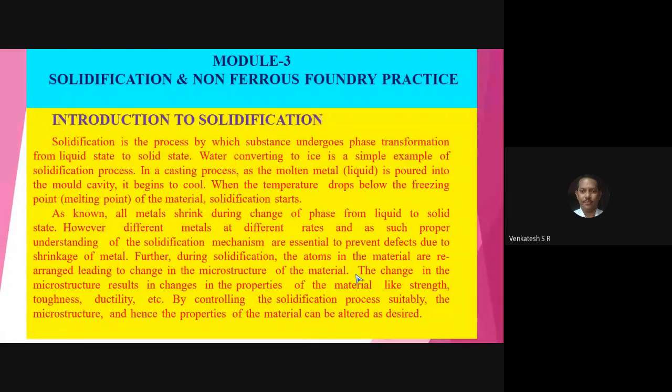If you provide heat to the metal in the furnace or in the oven or by other means, it converts into liquid phase. Pour the liquid metal into the mold cavity. Leave it for 2 or 3 minutes, depending upon size, shape, and type of metal. In a few moments, from 20 seconds to 20 minutes, the solidification takes place.